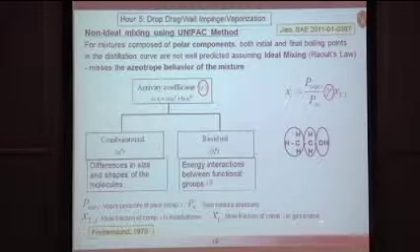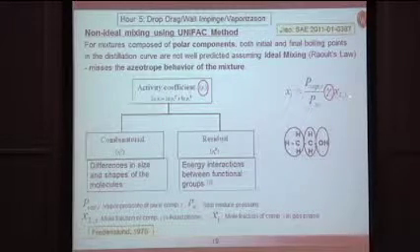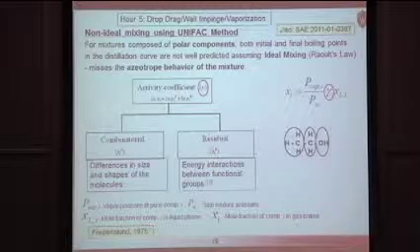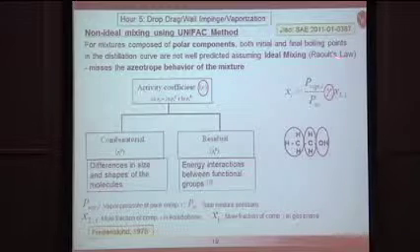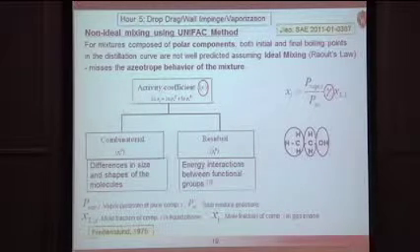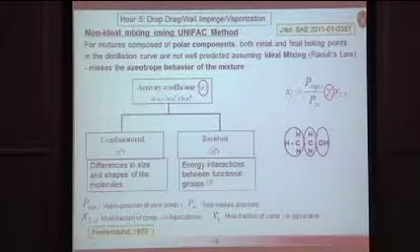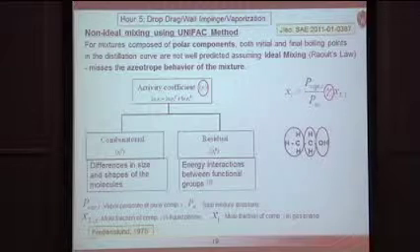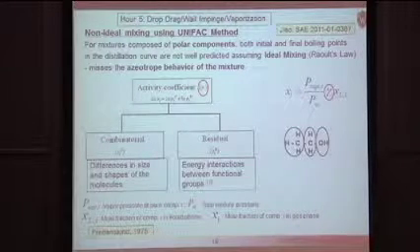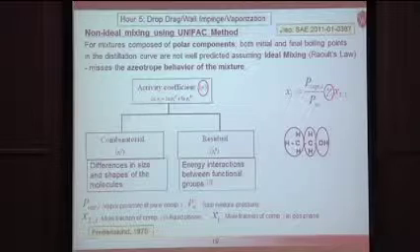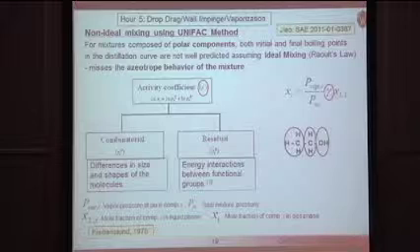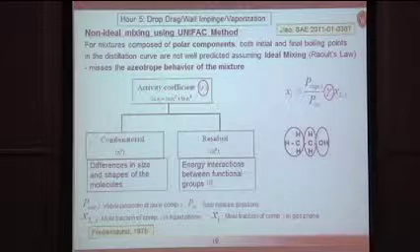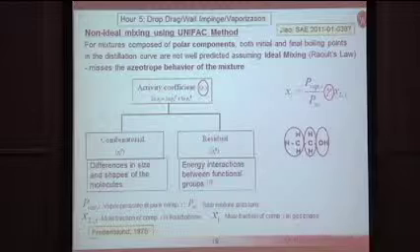the mole fraction of the component in the gas phase, is related to the mole fraction in the liquid phase by the ratio of the vapor pressure to the total pressure. That, in Raoult's law, is inaccurate for real fuels because one really needs to account for interactions, which appears through this so-called activity coefficient. There are many ways of calculating this, but the UNIFAC method is developed at NIST. It's a very popular way of handling this, and it accounts for interaction between the species.